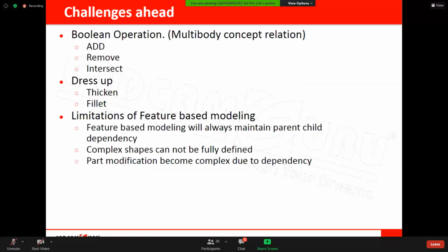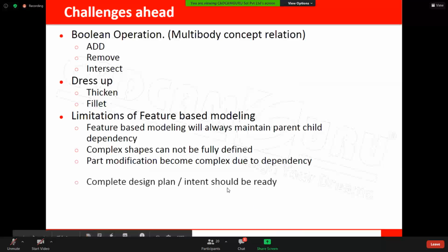Some dependent features are deleted, and how do you rectify that? How do you find a specific child feature, because my design tree or specification tree is very lengthy, since we are building thousands of features? In that situation, modifications create complexity. It is quite complex to rectify the problem and find exactly where it failed after some modifications. So that is the limitation of feature based modeling.